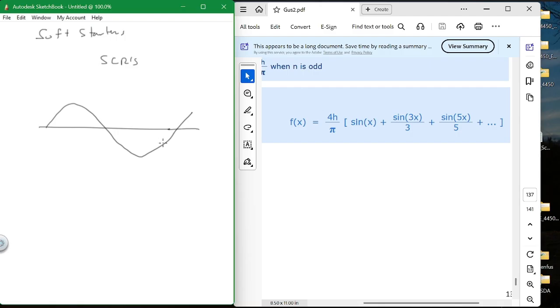and they only allow through a certain amount. So they start here, and they turn off when you go through zero. So you allow that much in. So you turn it on right here, and you only allow that much in. Then you turn it on a little bit later, and you allow this much in. You keep moving it across until you finally let the whole thing in.